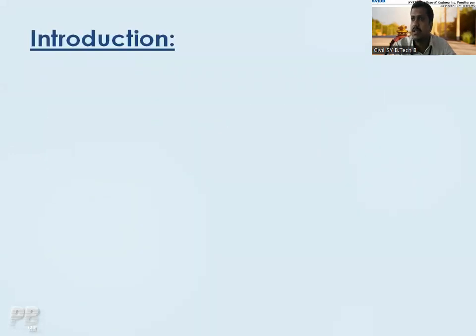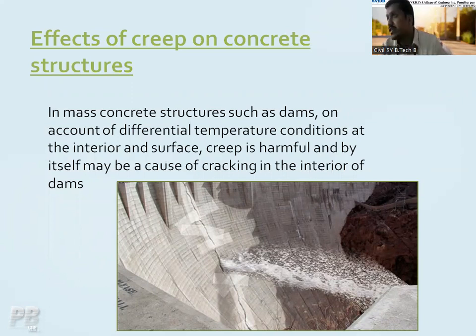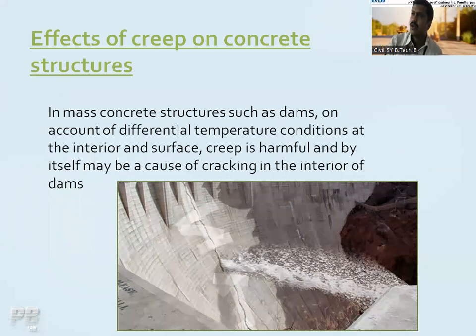Then the last part, I gave you the example of a dam construction site. If creep occurs on a dam construction site, that is, if there is a deformation, what will happen? Though it looks very simple, just a minute crack developed on a dam site, it is not a minute crack. It may lead to the failure of the dam completely if you do not take care of such cracks or such deformation.